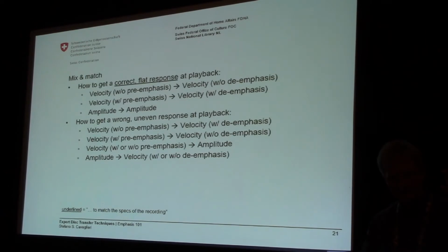If we cut with a velocity-sensitive device without pre-emphasis, we need to play back with a velocity-sensitive device without de-emphasis. Same thing if it's with pre-emphasis: we need to play it back with the same or a similar de-emphasis. Or the other option is if we cut a groove with an amplitude-sensitive device, we should play it back with an amplitude-sensitive device again.